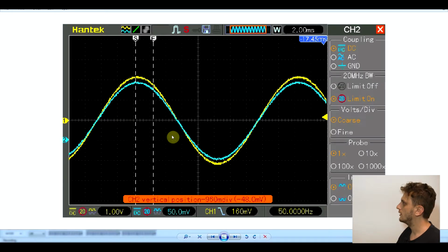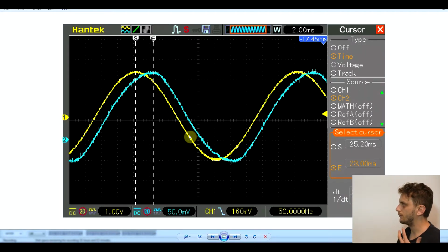Normally, with the resistive load, the one that we looked at previously, both the voltage and the current have the exact same polarity. When the voltage is positive, the current is positive. When the voltage is negative, the current is negative. That means that power is flowing from the power supply to the load. Now if we look back at our inductive load, we see that when the voltage turns negative, our current is still positive. So for a brief moment, rather than supplying our load from the generator, we're supplying the generator from the energy stored in our load, in the magnetic field of the inductor.